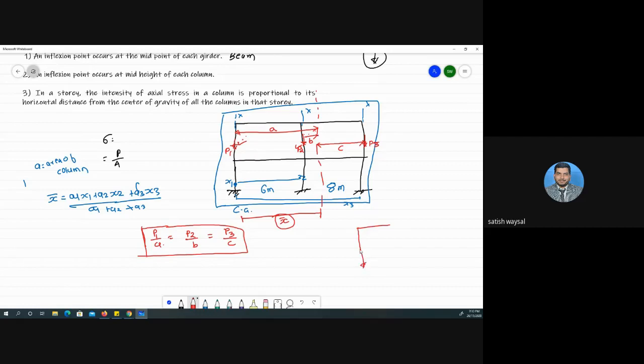Now this force is known to you. This is your horizontal force. Now what we have to find out? DCH, the vertical reaction by applying summation Fy, and if there is a horizontal reaction, by summation Fx equal to 0. So the overall procedure will be similar to this.